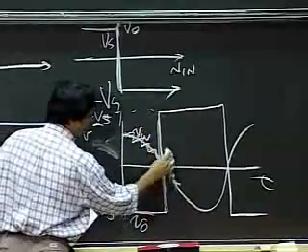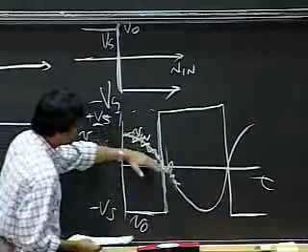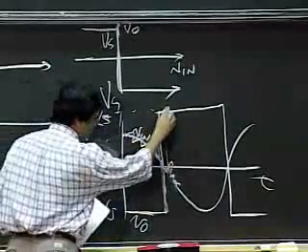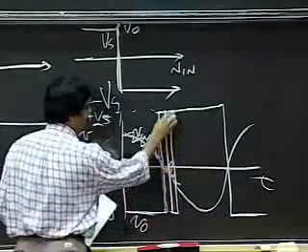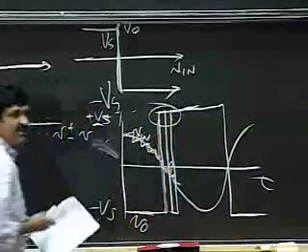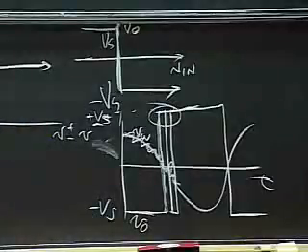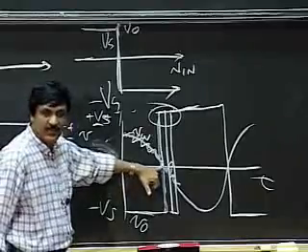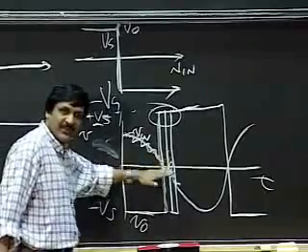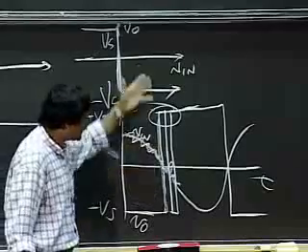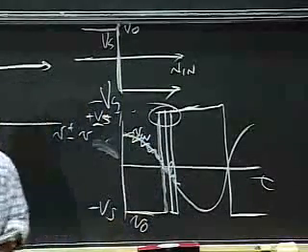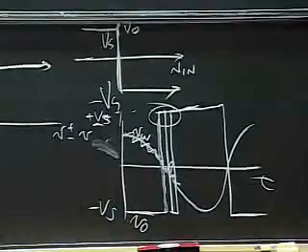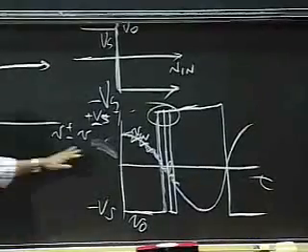But when, for a second, my input goes above 0 again, this output comes down, and out here it goes up again. So I get this nasty behavior at the point where the input is around 0. When the input is meandering around 0 because of noise, I get a huge amount of up and down glitches on the output. That's not very nice, and we'll do a little circuit that attempts to fix that problem.